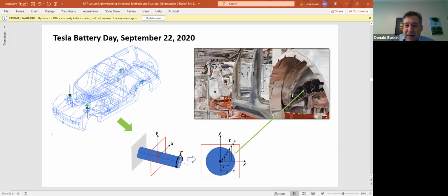Another topic that Elon Musk discussed, which I thought was interesting, was the floor pan. They're going to use the battery cells as structure to support the bottom of the vehicle, the floor pan effectively. So the battery's on the bottom of the car, and there's some skin on the bottom of the car. And then if it's going to be some type of sandwich structure, they'll have two panels separated by some distance. That's sort of like a carbon fiber honeycomb panel, if you've maybe seen one. The honeycomb separates the skins of two pieces of carbon fiber.